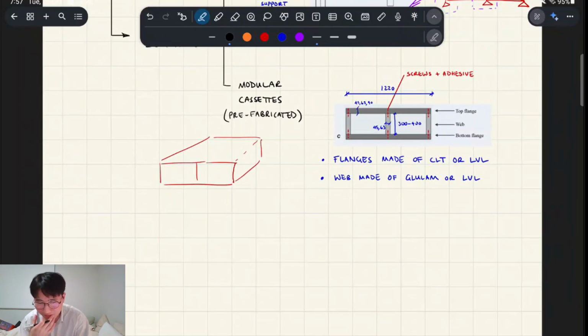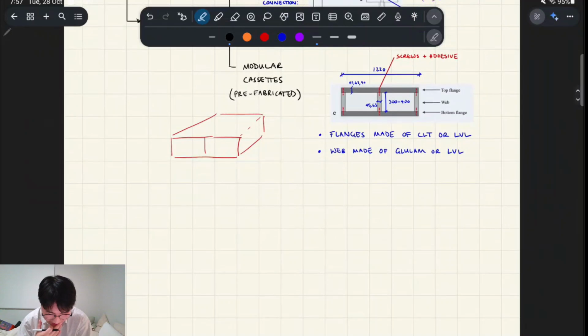Unlike concrete, if you're forming these as suspended slabs, you don't need to prop it as it's curing. Like prefabricated timber, you don't have to wait for concrete to cure to gain its full strength. So timber allows fast paced construction on multi-story buildings and stuff. So that's one way to use it.